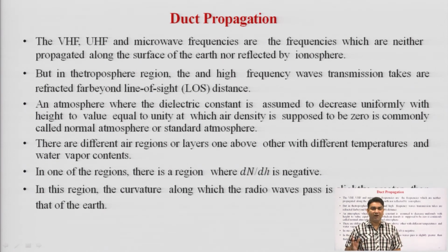So, apart from all these conventional modes of propagation, duct propagation is also a very important mode of propagation which utilizes frequencies in a very high range, and the distance can be extended up to thousands of kilometers. But in the tropospheric region, high frequency wave transmissions are reflected beyond line of sight distance in this kind of mode of propagation.